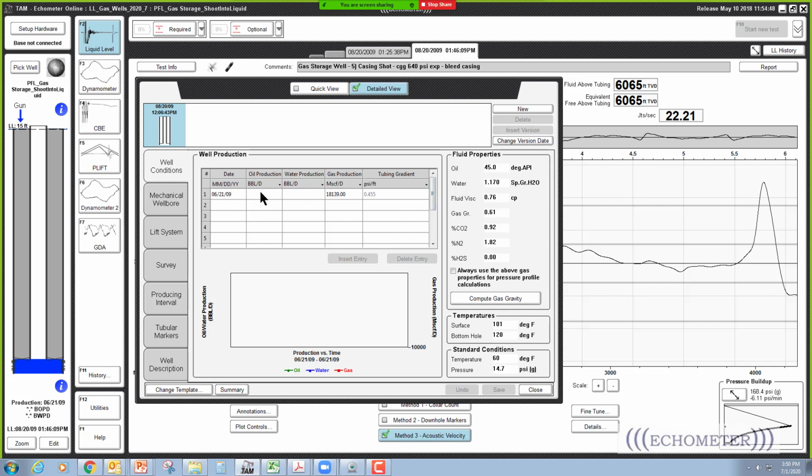We didn't have any production data in this well because there wasn't any water being produced. But we probably should put one water, so this would be calculated based on water and not based on oil. So if I was going to calculate the pressure at the packer, I'd put a 0 here and a 1 here. Okay, and I would type in the gravity of the KCl water, 1.17, and then when I save this, it's going to change this to be blue, and then the pressure here is going to be calculated correctly.